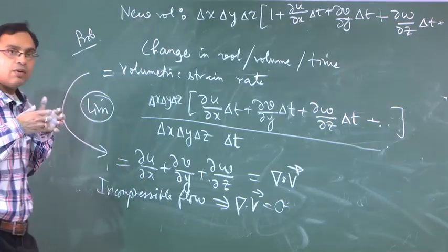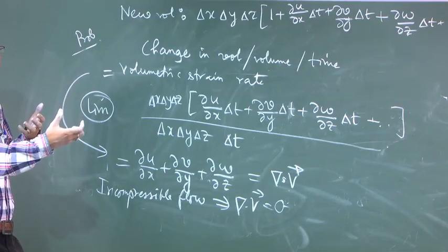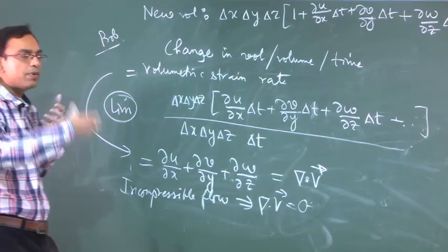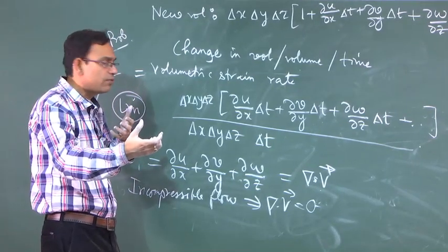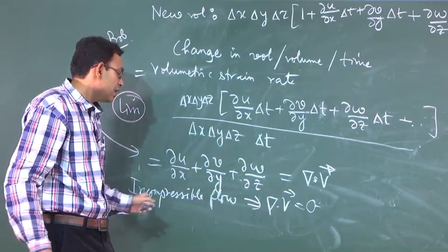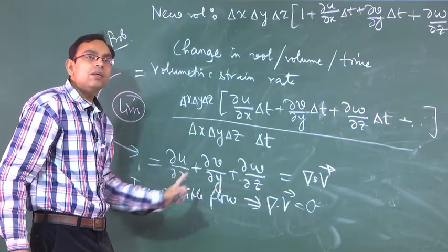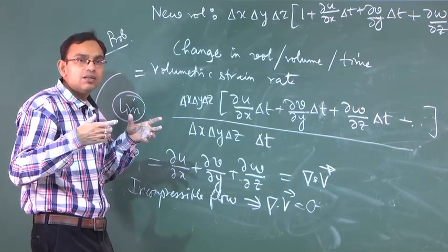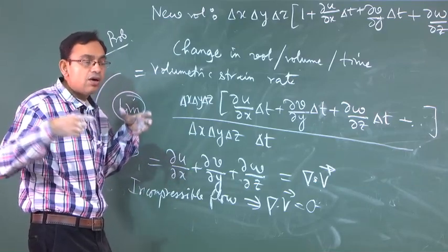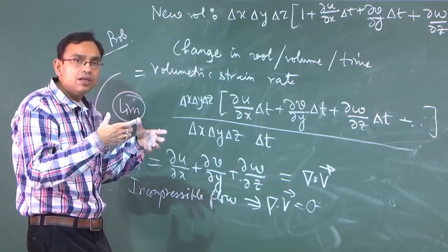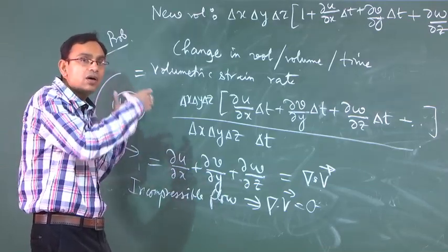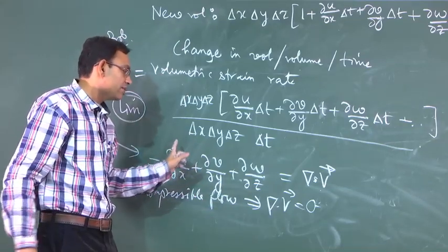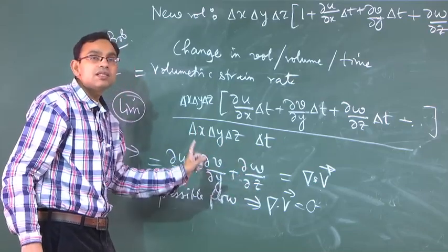So, that is another way of looking at a fluid, as a property representing the characteristic of the fluid, and here incompressible flow is more of a kinematic definition. So, looking at the situation as a compressible or incompressible fluid is one paradigm, and compressible and incompressible flow is another paradigm, and incompressible flow essentially follows from this kinematic constraint.